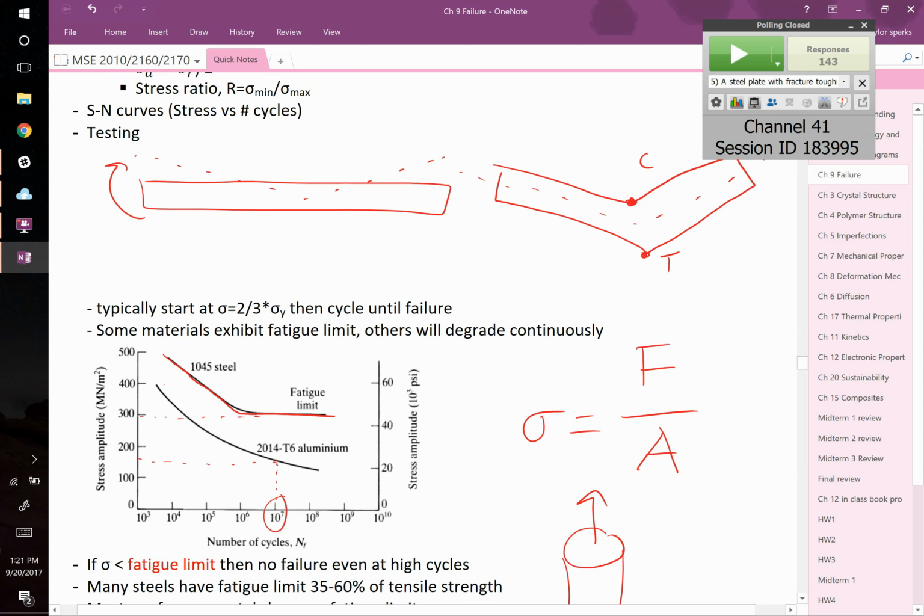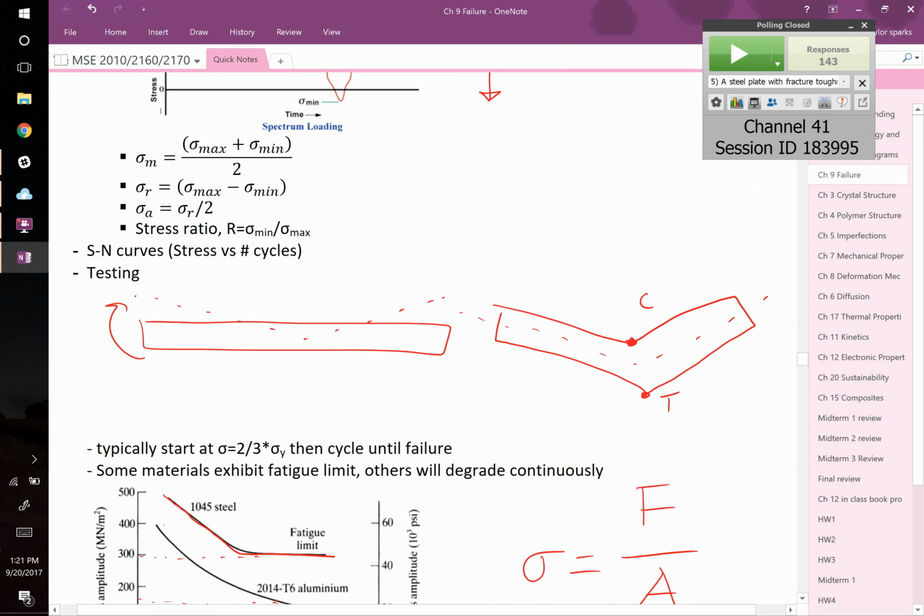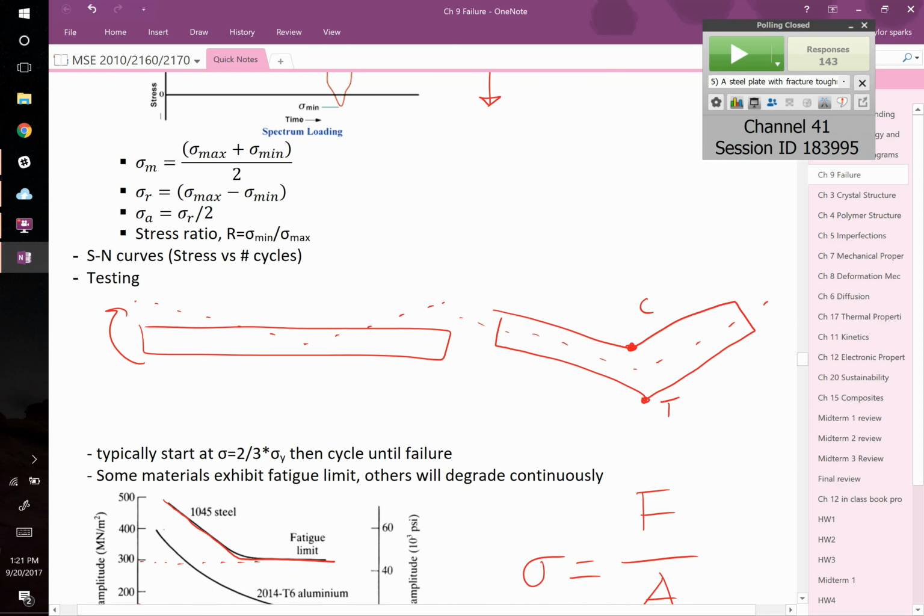Okay, Rosa? Are those stress amplitude graphs based on the theoretical stress? No, they're based on actual tests where they took a rod, bent it slightly, something like a half a degree, and spun it until they observed some sort of failure, whether that's it deformed over a certain amount or actually fractured. Depends on whether it's ductile or brittle. But no, these are experimentally calibrated.